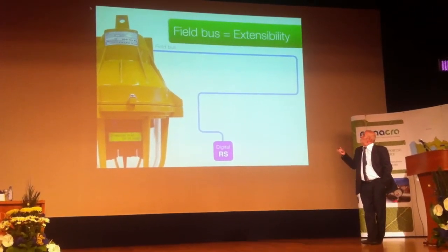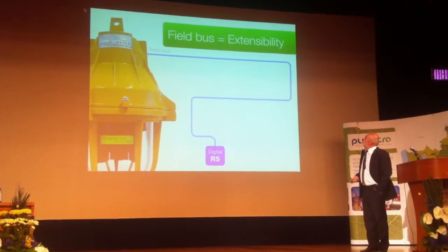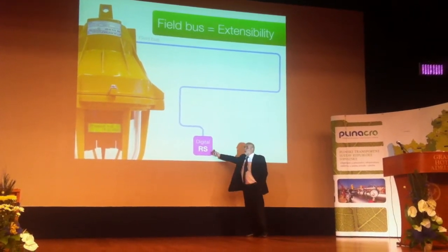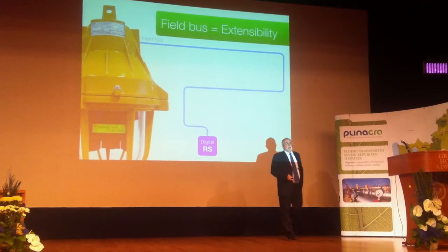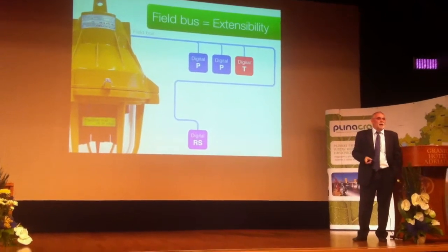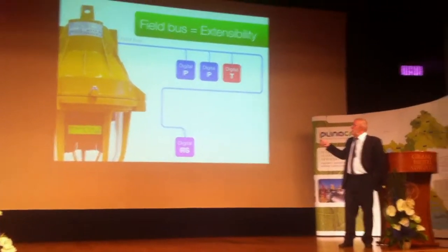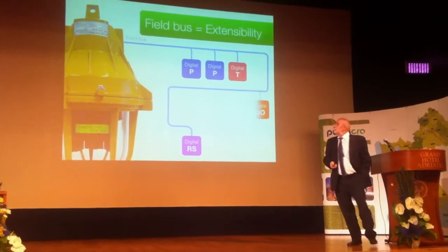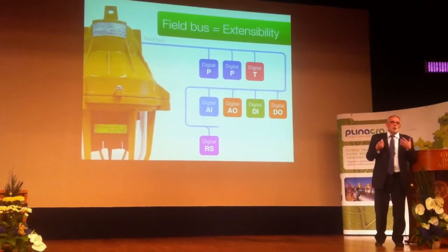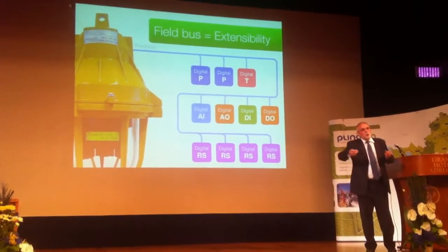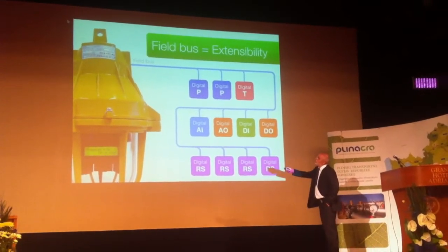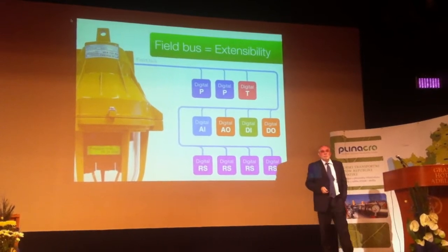Field bus in our concept as gas people is equal to extensibility, which means that if I need to acquire data from one single corrector, I can do it as I can do it with anything else. But if I want to extend it with a few pressure measurements, I simply extend the bus with the necessary field bus devices. If I want to extend it even more, then I put even more devices on the field bus. If I have some more correctors, then I put protocol converter modules on the field bus. But don't forget, all these are working from the batteries which are inside this device. And they are working for a long time.